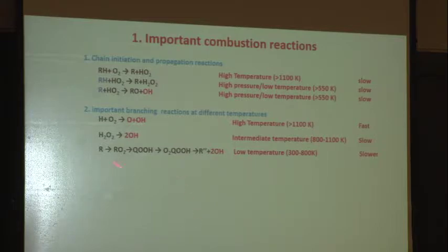If we talk about low temperature chemistry and you want to control it in an engine, for example HCCI, ignition timing control is difficult. Plasma has the opportunity to control the ignition timing because low temperature ignition is very easy. But the question is how do you generate a good plasma to control a big volume, right? That is a key question. How do we design a non-equilibrium plasma that can generate a volumetric discharge to control the ignition?